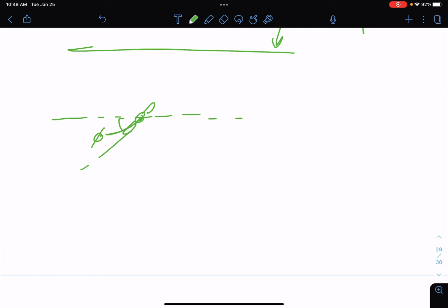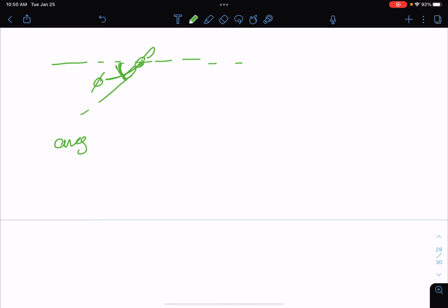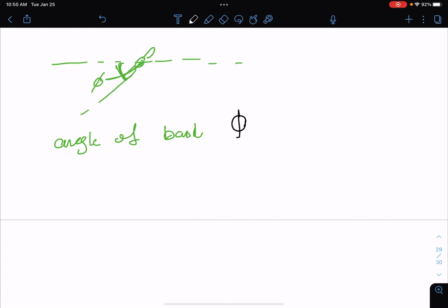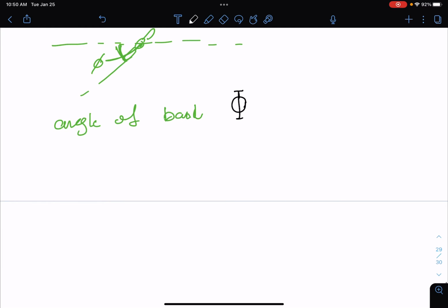And that curve is also included in the angle of roll. That's why we defined another angle that only looks at this angle, and that angle is called the angle of bank. Angle of bank is shown with the capital letter phi, which is essentially defined as the angle between YB and its projection on the XE-YE plane. YB and YB's projection.